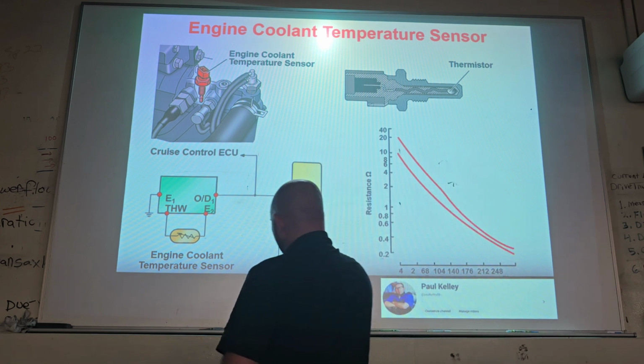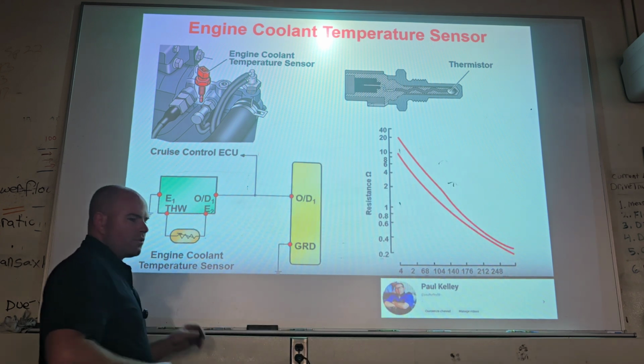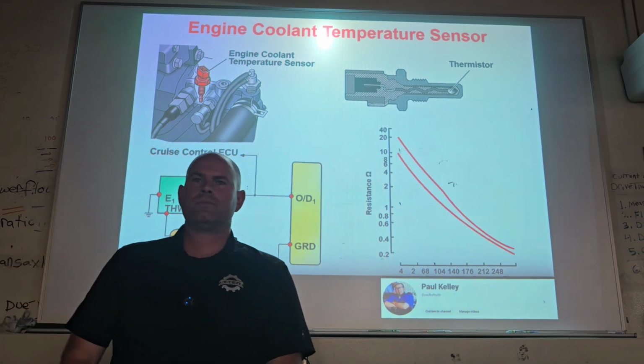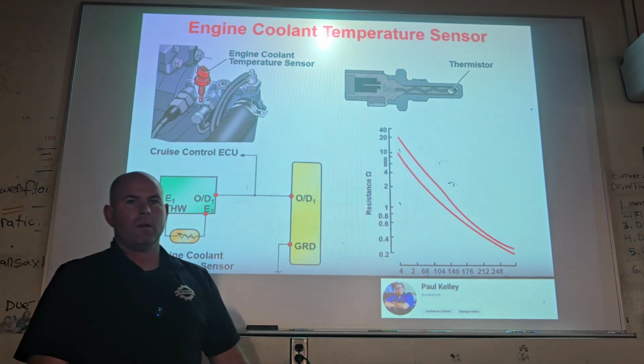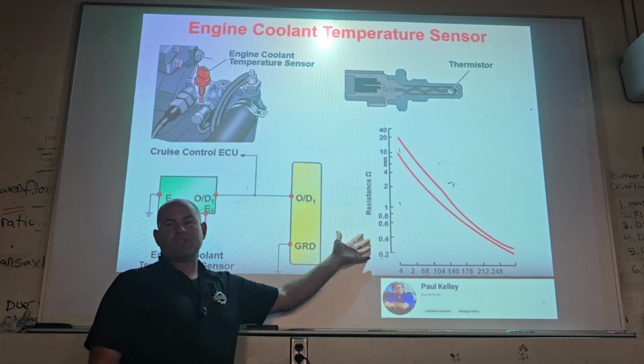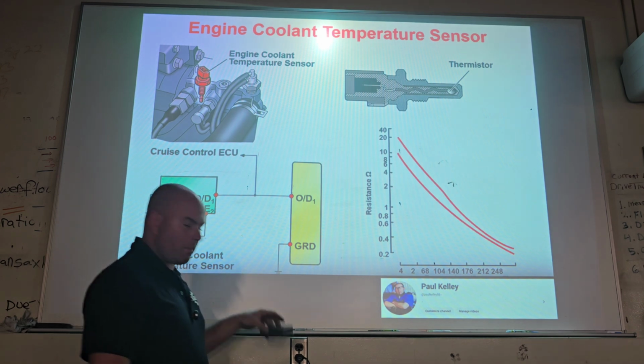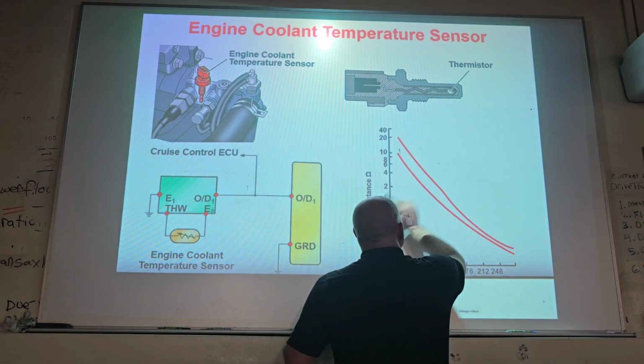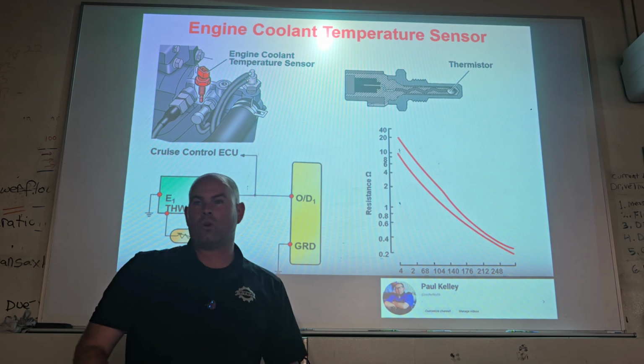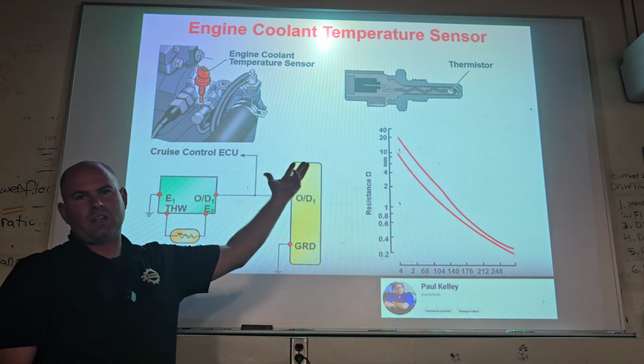Now, why do you think engine coolant temperature is part of transmission diagnosis? Do you think the transmission is going to shift the same if it's a cold engine versus fully warmed up? Exactly, because we don't want it to shift the same if it's a cold engine. So this can have an effect on a vehicle.